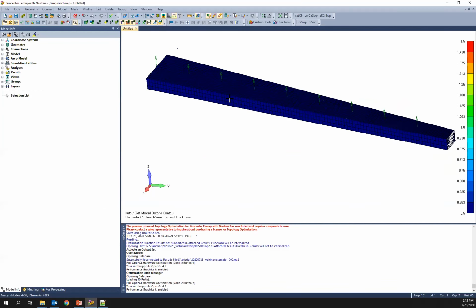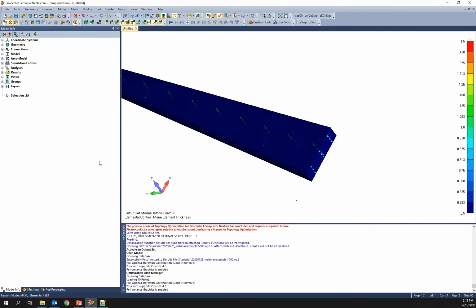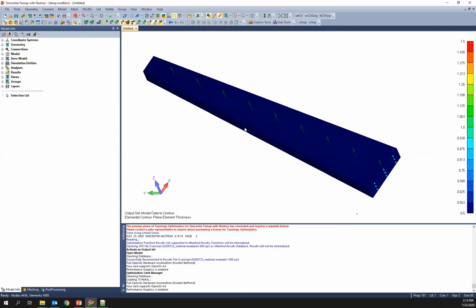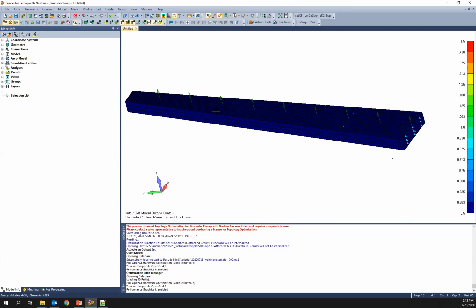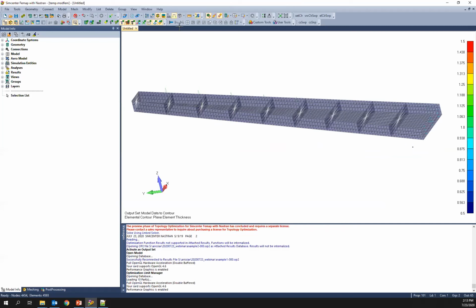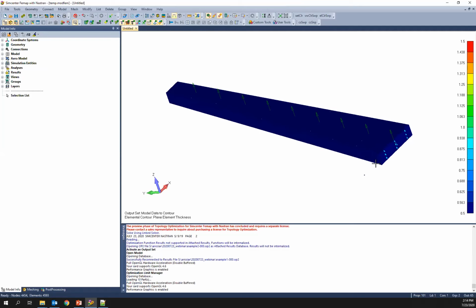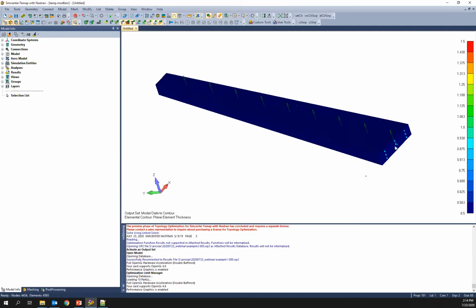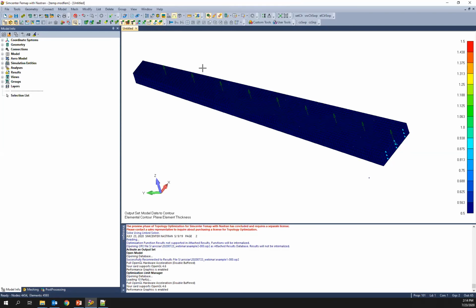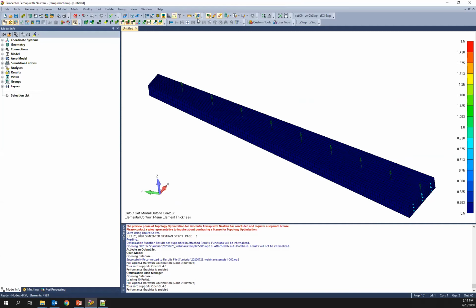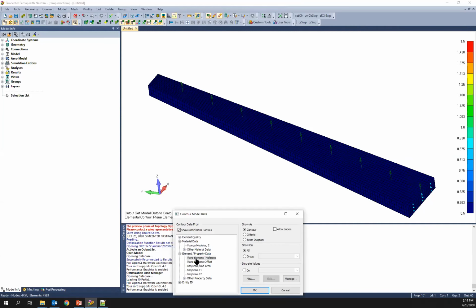So this is the wing model. I have a load case applied that corresponds to the 4.4 G maneuver load, applied at certain ribs where the distribution is localized to approximate the wing aerodynamic load. So I'm just looking through this model now. We have a constraint at the root and loads applied. I want to look at the initial thickness values, which I think are displayed right now.